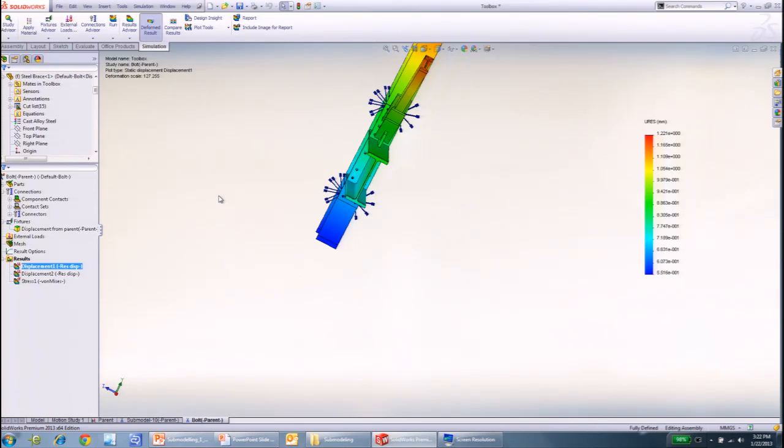But again, with simulation, your assumptions give you the right results, right? So you need to make sure that your displacement at least converges on the master model before you start running it. That's something you'll have to do. There are no tools here because of submodeling to help you do that. That again is left to the engineer to do.